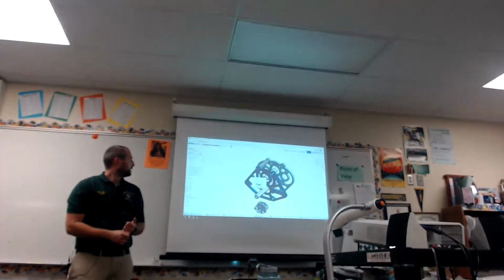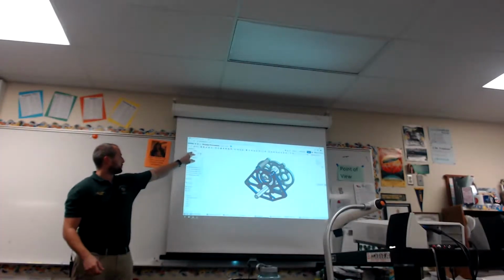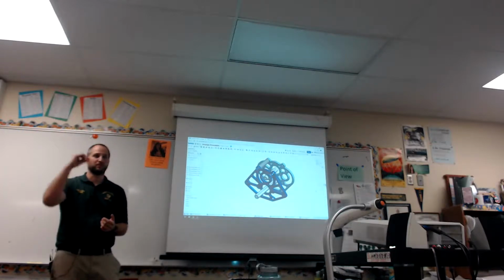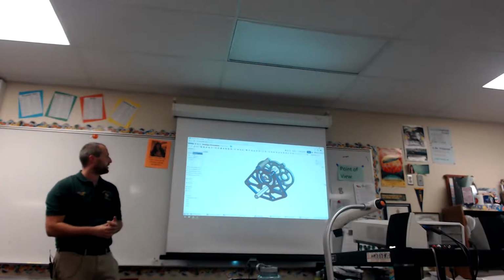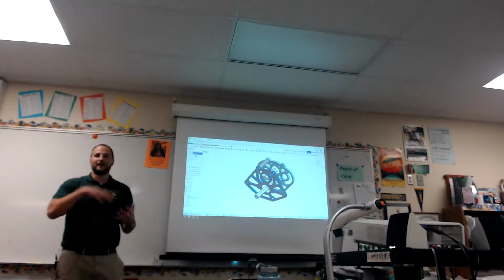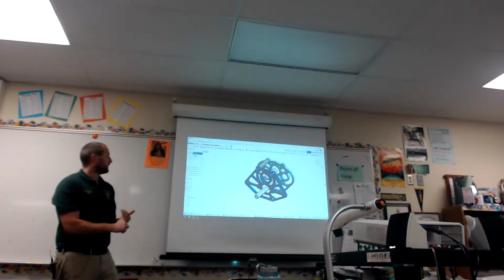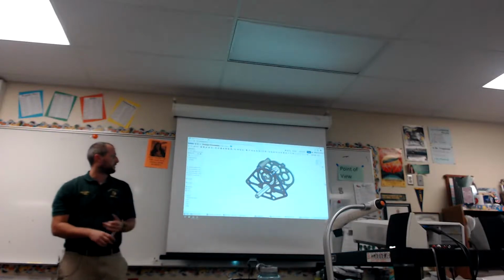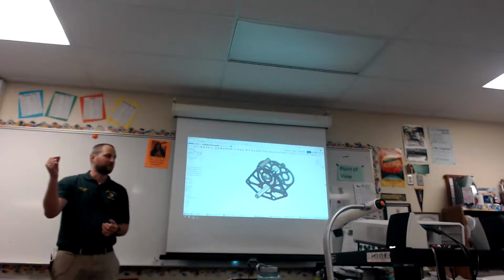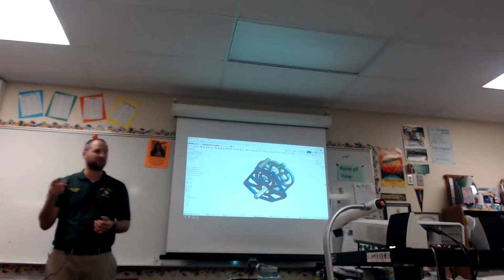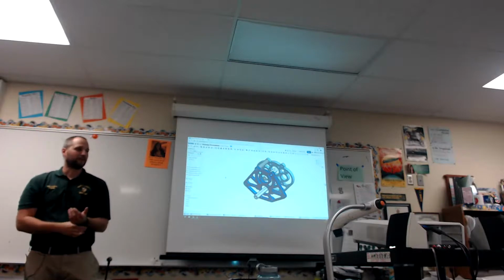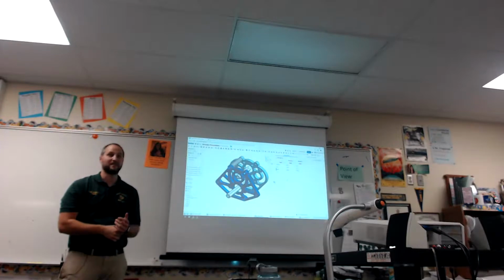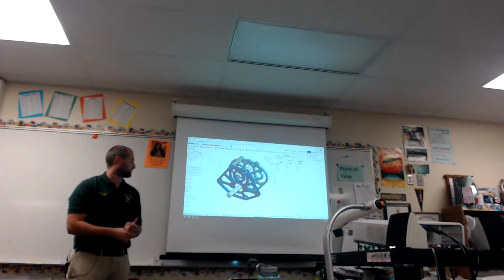Configurations. Yep. And you can see there's this input up here at the top where if you have some parts that you want to change and you want them to change between specific values, or you can program variables. So I took these variables that he had made and I changed them into 3 distinct inputs: a default value, a thin gearbox plate, and a thick gearbox plate. And so now if he changes it to thin, everything changes down to 0.125. If he changes it to thick, all those change out to 3/8. It's just another thing that you can see. It's kind of helpful, beneficial. And that's really easy to build out. You just click on the flyout and adjust some things.